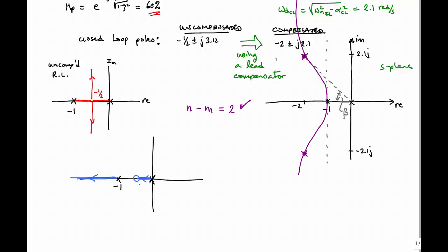And we might say, well, hey, we can position a closed loop pole right here at -2, right? That's good. However, our second closed loop pole is going to sit somewhere between 0 and -1. I have a closed loop pole that's now going to sit somewhere between these two. Say I'll put it right here.